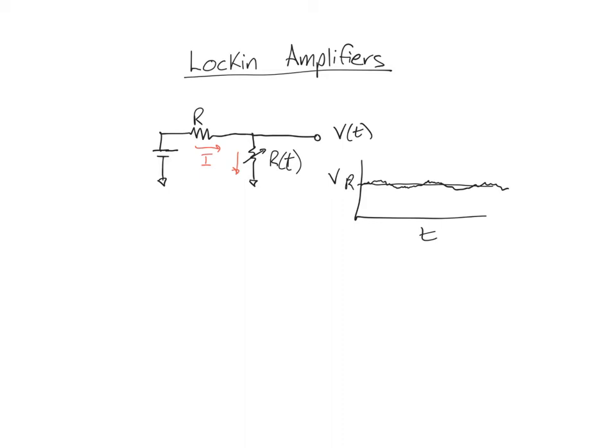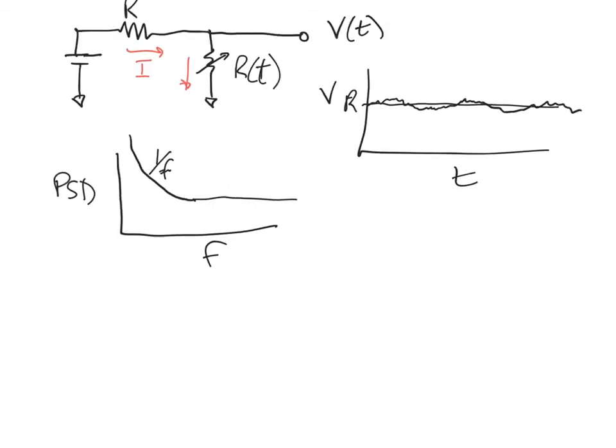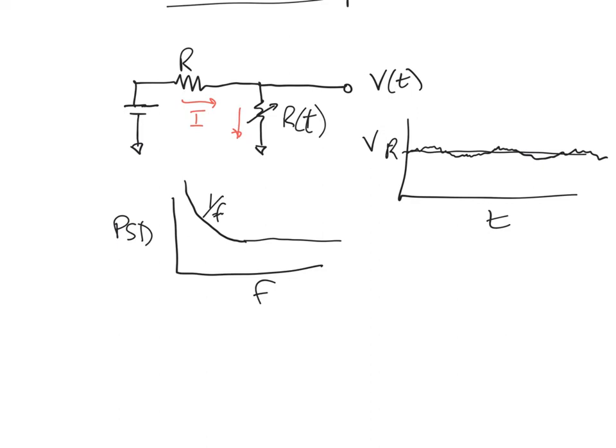And if I take the Fourier transform of that, and then take the power spectrum, then in frequency space, the power spectral density as a function of frequency will in general, out at high frequencies, look like white noise if things are working well. So there's just a certain noise level associated with the Gaussian random noise. But the drifts and things like that will tend to have what's called a 1 over f component. So it will be red, in other words, long wavelength, low frequency components will tend to have higher amplitudes.